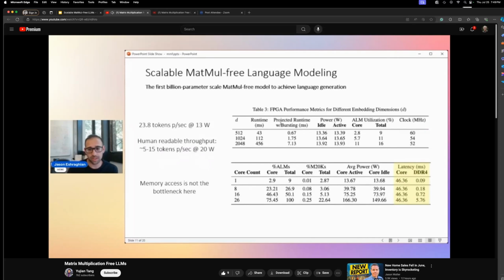At the moment, it turns out that the 3 required ternary accumulations, and in the paper we do call it a ternary matmul, those instructions take up nearly all of the total execution time. So in future work, if we were to introduce parallelism and caching to improve the ternary matmul execution time, then that could lead to a huge change in the balance between core and DDR latency.